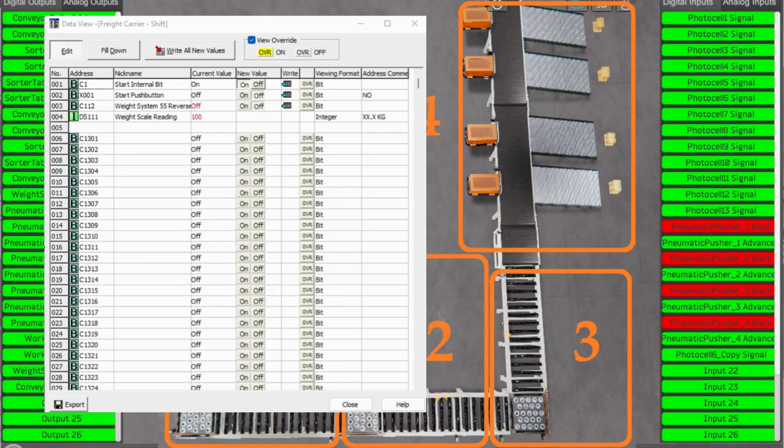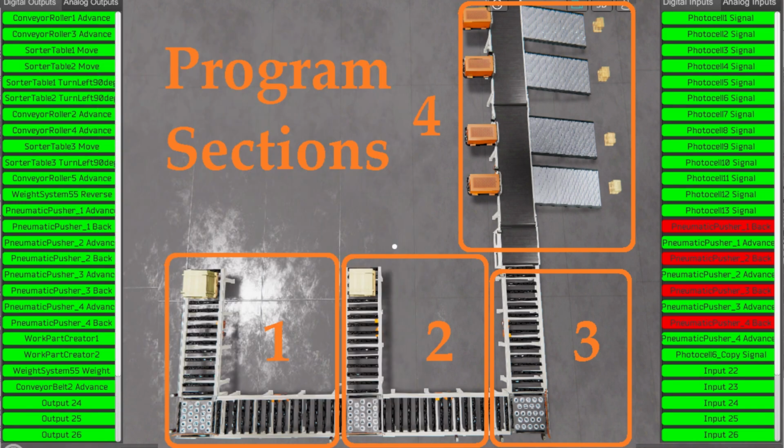Now, a PLC programmer must know everything about the sequence and operation of the machine before programming. Writing out what is supposed to happen will help you clarify what is required in the PLC program. This is just another method like flowcharts and sequence tables, so ask questions or view existing documentation to ensure that you know the logical steps of the machine operation.